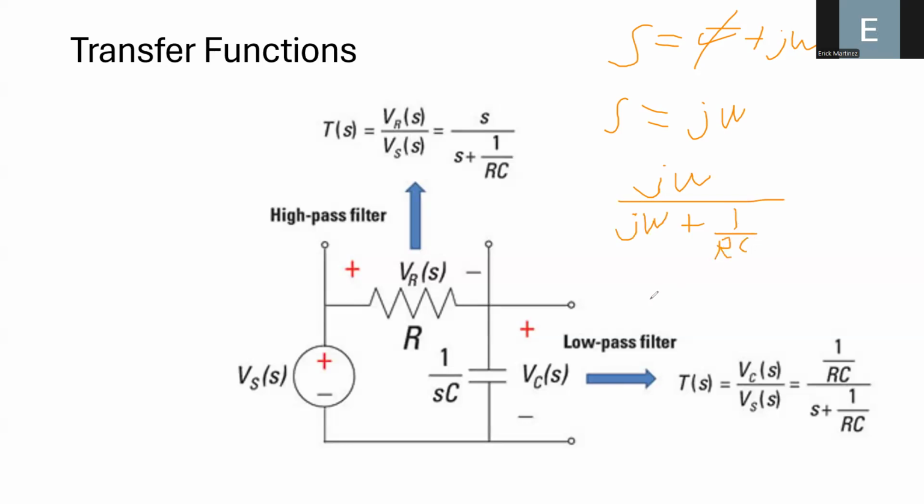Okay? So what we can do is say, I can place a value of the resistor as I want and a value of the capacitor as I want, and I will have a function that depends on frequency. So to simulate or generate this Bode diagram, I can plot the behavior of this transfer function by changing the values of omega between 0 and infinity. And I can do the same for the transfer function on this side.